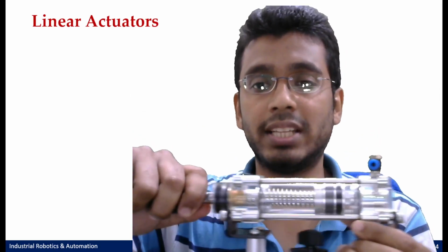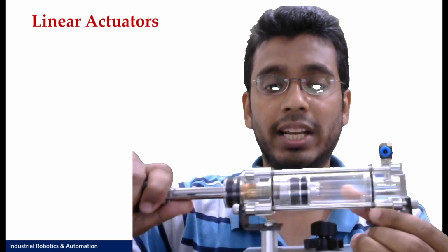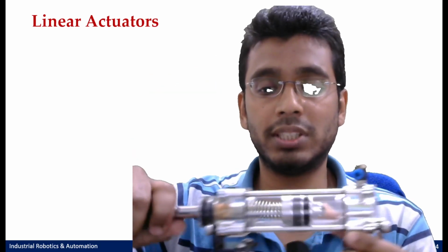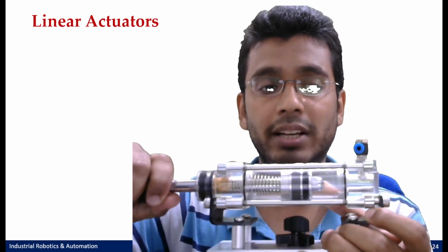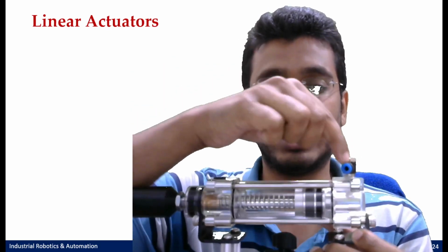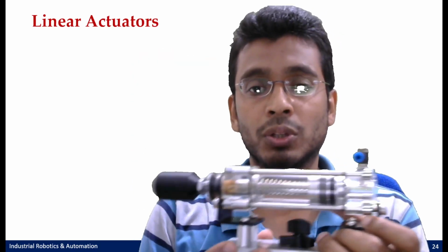Okay, because to extend this again, it has to release the gas that is present on this side of the portion. And when it is retracting back, this will act as a drain port, because the spring is acting as a force to retract it back. At that time, when it is retracting, the unpressurized fluids have to flow from this line. Okay, so this is one.